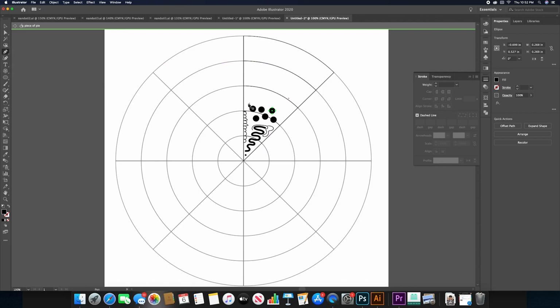Or I can go with the pen tool and draw out a little bit cleaner lines. I click a point, move over to an area, click and drag to help create a curve. And right now I currently have a fill color, but I can switch this over to my stroke. I can hit escape to end my line and then look to draw out another line through the design. Once I have the line, I can hit escape again, continue this process for however many lines you like. Or you can look to mix it up, experiment with different curves or zigzags. Maybe it's looking to change as you get into different sections. Each section can have its own look.